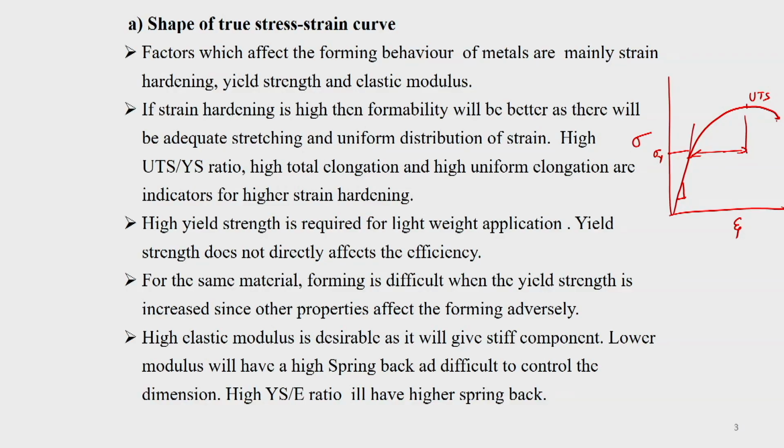Okay. So, it is difficult. When the yield strength is increased, other properties like toughness and ductility will get reduced. So, that will be adversely affected, and one has to be careful about it. If you have a higher capacity machine, then it is better to deform the material at the higher yield strength value. But if the capacity of your machine is less, then you have no other alternative than to give heat treatment and reduce the yield strength.